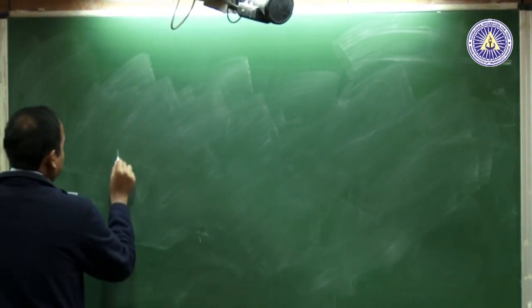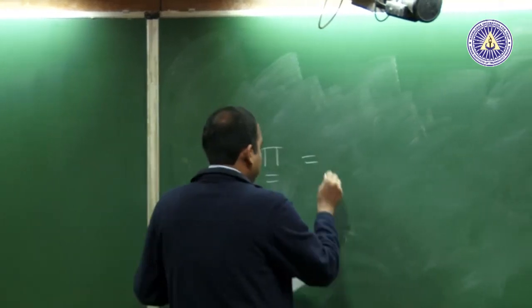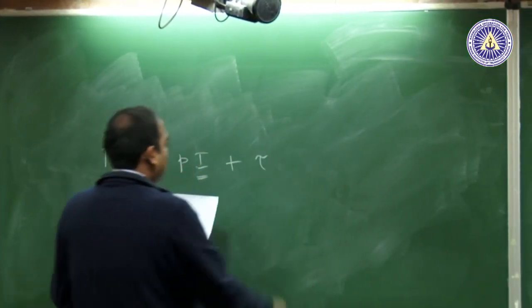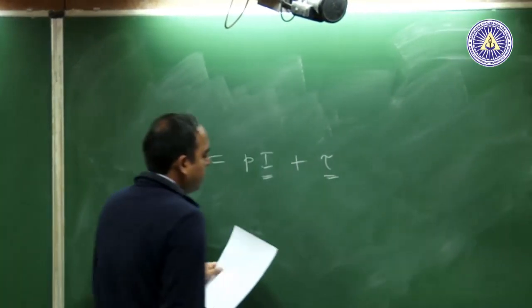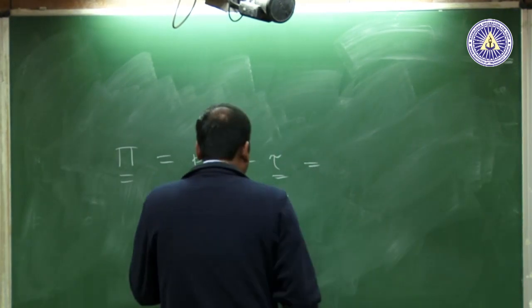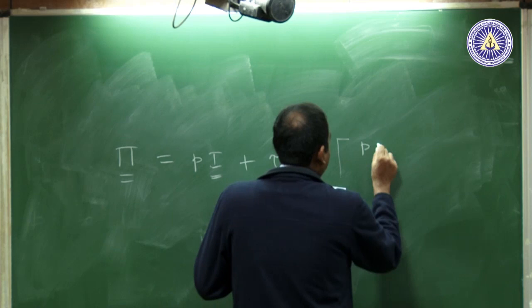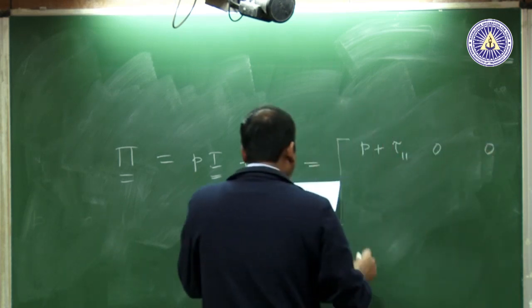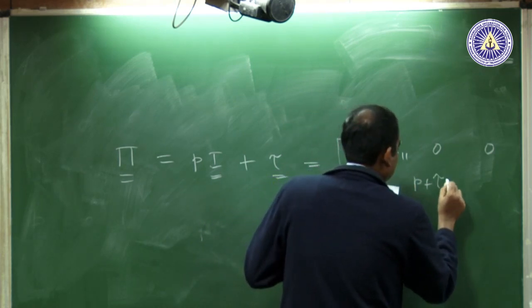So, when you measure stresses, you will only get the total stress tensor. The total stress tensor has a pressure contribution and the contribution from the deviatoric stress. Deviatoric stress is produced by the deformation of the fluid elements. Now, for a uniaxial extension flow, this would mean a stress tensor like this, in which I have the diagonal elements non-zero and all other elements 0.